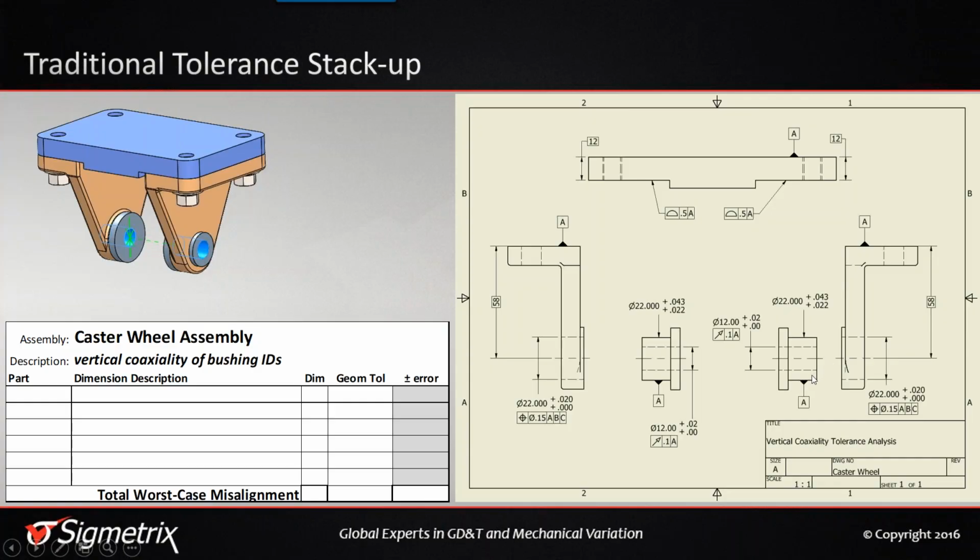Basically an assembly level view, but with part level details of how they're going to be controlled. Now, these particular parts have had GD&T applied. I will show both. I will do it in EZtol with linear dimensions and tolerances, and then I will modify those to show how the GD&T is defined within the tool, or GPS for the ISO standard.